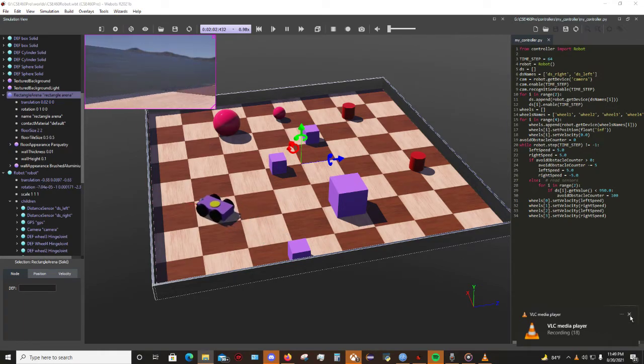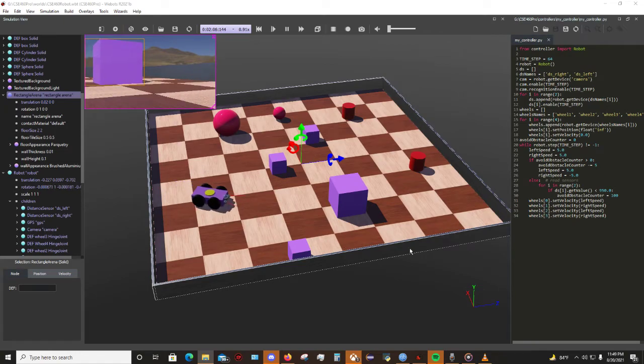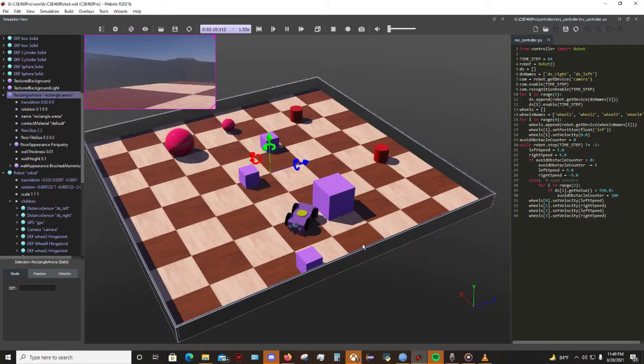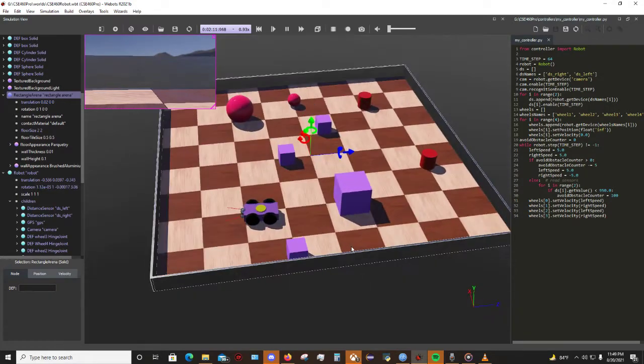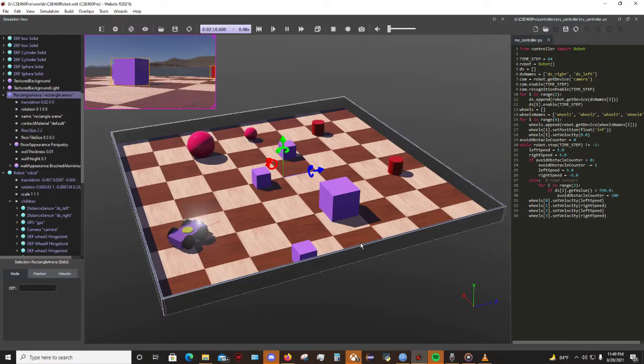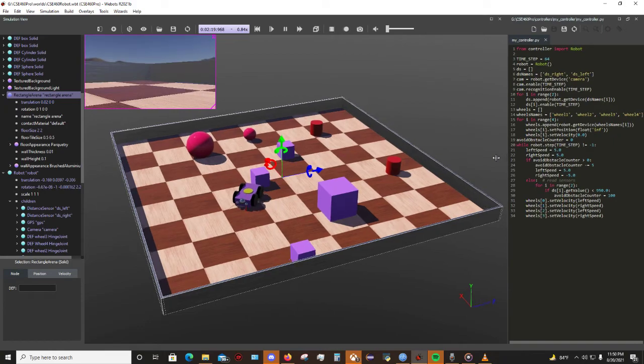Assalamu alaikum. I'm Muhammad Anwarul Azim, and I'm going to display the code behind our system. The code is written in Python, and we are using the robot module imported from controller to call the devices and assign values. We are using the getDevice method to do that. And there are three types of devices: two distance sensors, one camera, and four wheels.